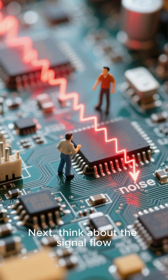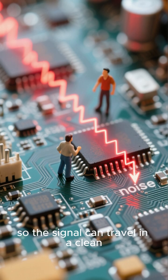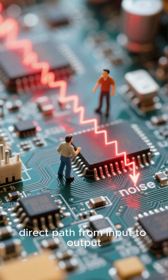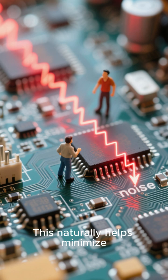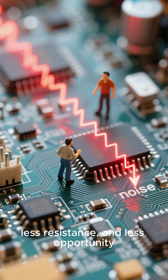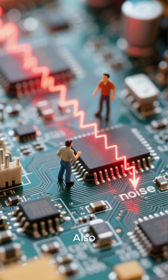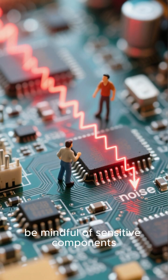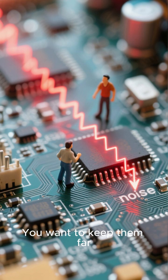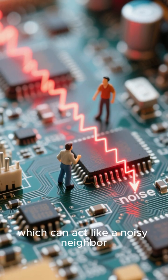Next, think about the signal flow. Arrange your components so the signal can travel in a clean, direct path from input to output. This naturally helps minimize trace lengths. Shorter traces mean less delay, less resistance, and less opportunity for noise to creep in. Also, be mindful of sensitive components. You want to keep them far away from anything that's high frequency or high power, which can act like a